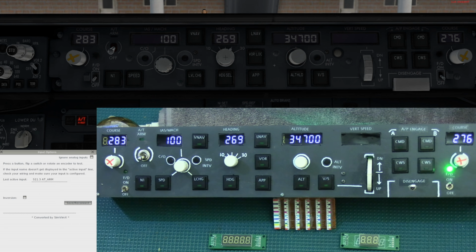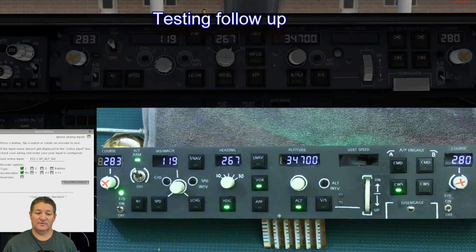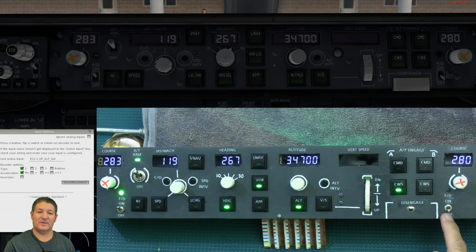All right, so that's better. Okay, well, I guess I just couldn't leave well enough alone, so I decided to try to figure out what the problem was with the encoder over here and the flight director switch. So what it ended up being was that I had put one of the leads for the encoder on the place where this one should have been, and then I put this one on the last one where the encoder should have been. I have the LED connected to that switch and it's connected to 5 volts. That's why it was acting weird. When I was turning the encoder, it was activating the flight director switch on and off. So anyways, I solved that problem.